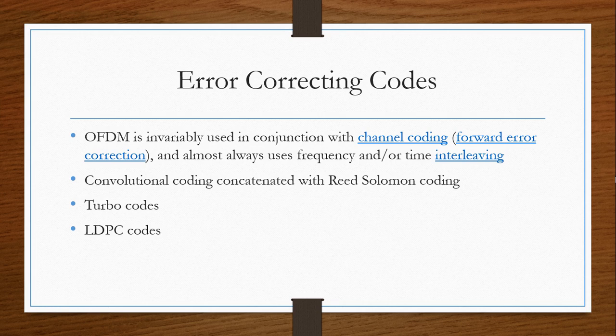An LDPC is constructed using a sparse bipartite graph. LDPC codes are capacity approaching codes, which means that practical constructions exist that allow the noise threshold to be set very close, or even arbitrarily close on the BEC, to the theoretical maximum, that is the Shannon limit that we all know, for a symmetric memoryless channel. The noise threshold defines an upper bound for the channel noise up to which the probability of lost information can be made as small as desired. Using iterative belief propagation techniques, LDPC codes can be decoded in time linear to their block length.